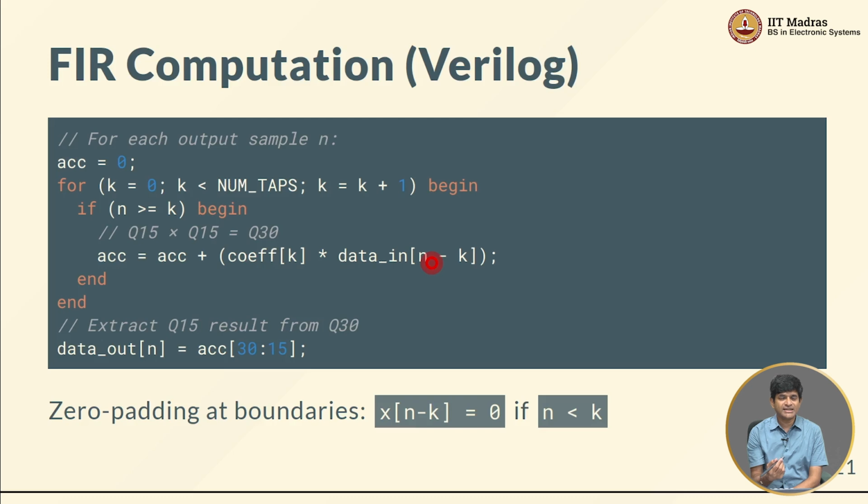But in our case, we are writing Verilog, it is RTL, we hope it is synthesizable, but there is still one catch, which is that we are not yet simulating a post synthesis example. But it can be done. So Verilator doesn't really care whether you are simulating a gate level netlist or some kind of behavioral Verilog. As long as you can verilate it, it will work.